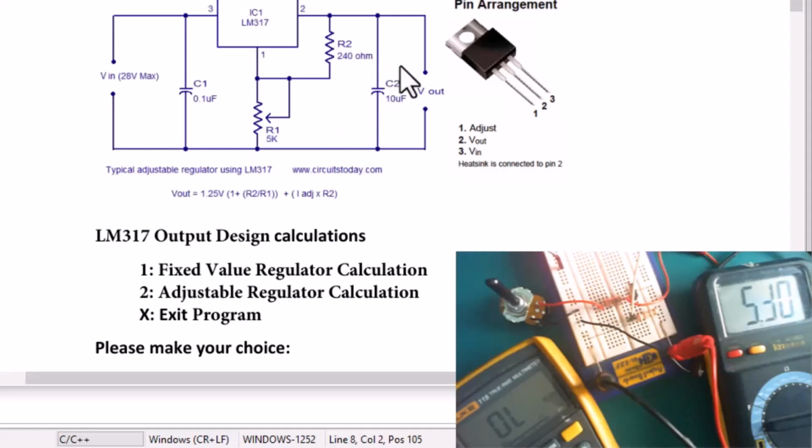They want a stable input voltage, because if the input voltage drops below a certain point, it might reset, and you do not want that. So to provide that stabilization, these capacitors on the output are very good. All right, and the one thing to note is this is a linear regulator, right? Because it's linear, the current on the input is exactly the same current on the output.